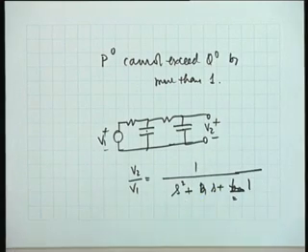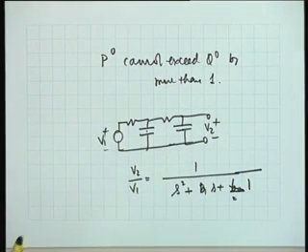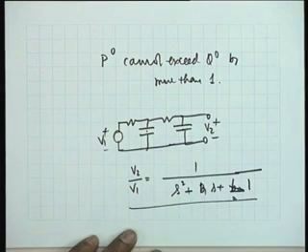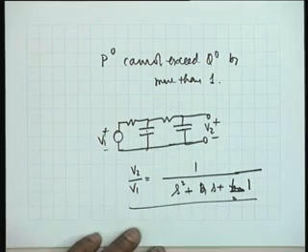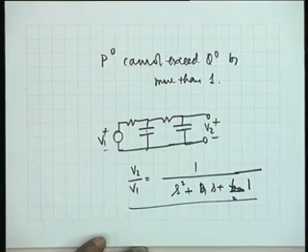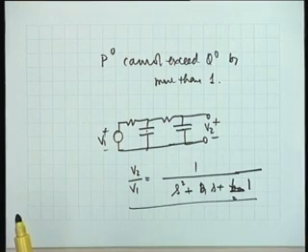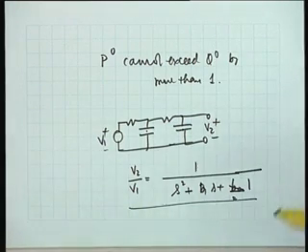And the reason is that if it exceeds by more than 1, we shall have a multiple pole at infinity. Here what is wrong, what is right here and what is wrong here? There is a multiple 0 at infinity, that is permitted for a transfer function. It is not permitted for a driving point function. Why not? Because the reciprocal of a driving point function is also a driving point function. And if there is a multiple 0 at infinity, there shall be a multiple pole at infinity of another driving point function, which therefore ceases to qualify as a driving point function.